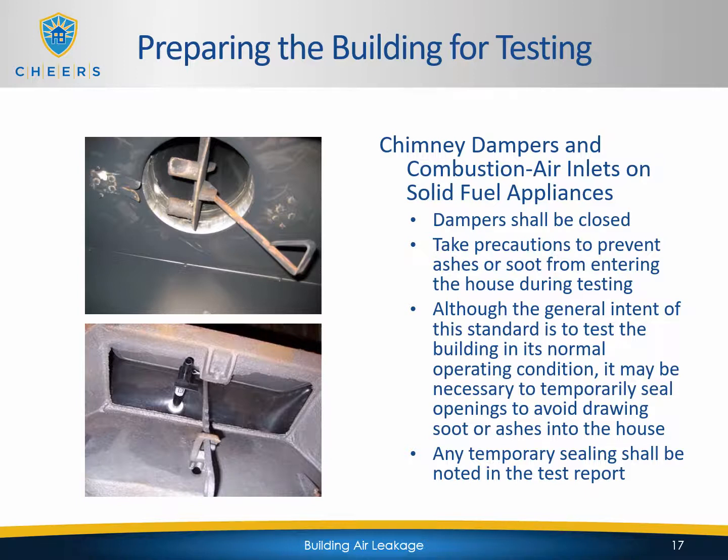So you will be depressurizing the house, meaning that you'll be sucking air outside of the house. When the blower door starts and you depressurize the house, the blower door is going to be sucking air from whatever crevice it finds within the house itself. If there are ashes or dirt or anything in the chimneys, in the appliances, or wherever it is that they may be, those ashes, that dirt, those contaminants will be pulled into the house and through the house, depositing on the carpet, making a mess, generally speaking, just causing problems. So that's why they allow you to do this if need be. Any temporary sealing, keep in mind though, shall be noted in the test report.